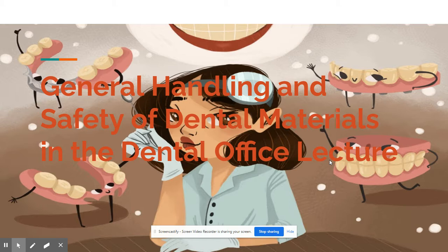An example of a regulation that can improve wastewater and groundwater is a regulation requiring use of an amalgam separator. The Environmental Protection Agency mandated under the Clean Water Act that in July 2017, dental practices must control amalgam waste through the use of amalgam separators certified by the International Organization for Standardization, ISO, Standard 11143. These separators can remove 95% of the amalgam fine waste and prevent it from going into the sewer system.